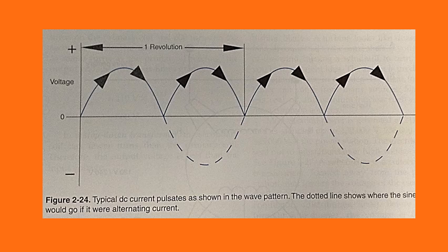Single-phase and three-phase electricity. An AC generator may produce either single-phase or three-phase electric power. A generator with a single armature or coil produces single-phase power. To produce three-phase power, the generator must have three armature coils.